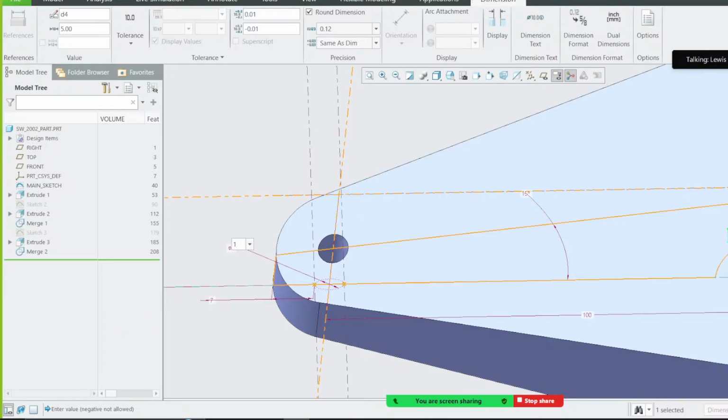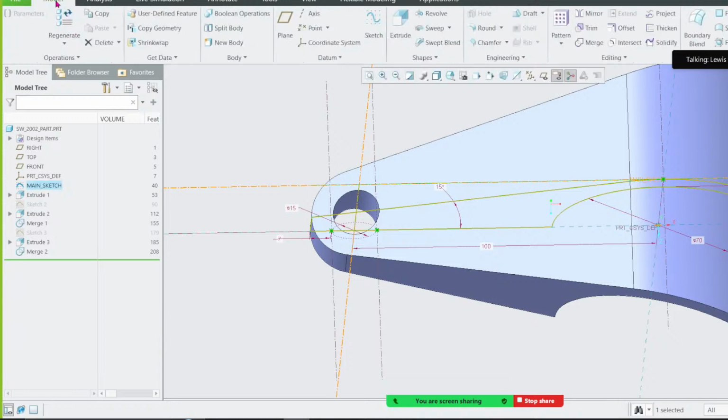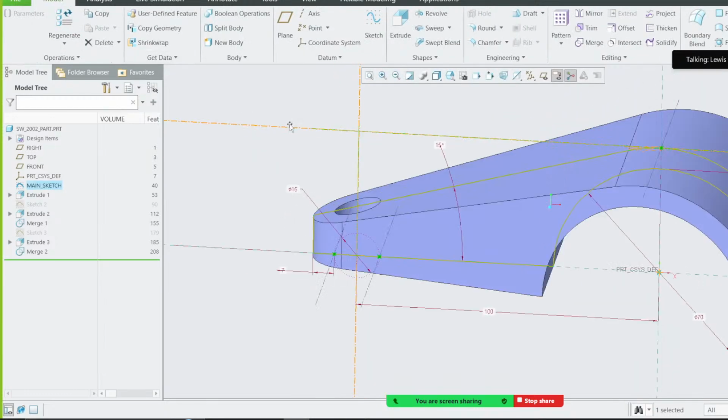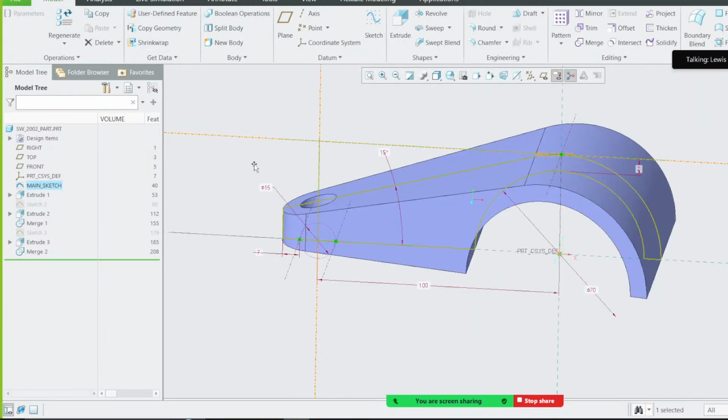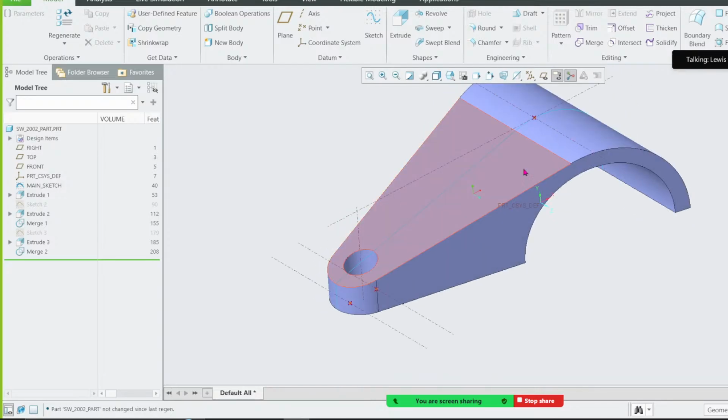All of them are going to change from one point of control. Therefore, that is what I'm insisting on today. Always make sure that your design is referencing one point. Avoid a lot of references. If you give someone this design now and tell them to modify something, they just go to the main sketch and change something. And my design is now very robust.